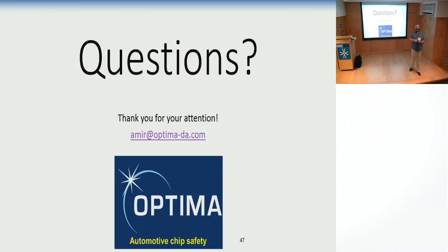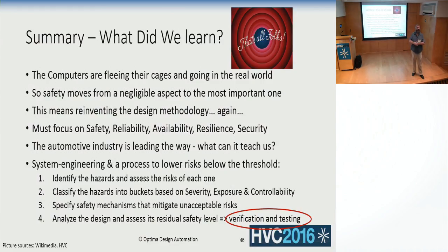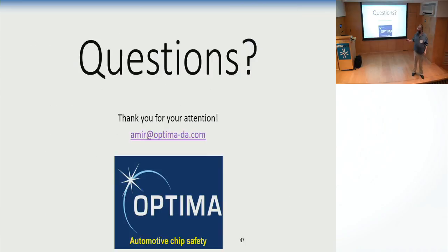We don't use statistical probabilities to figure out where an event will happen, but we do compute the probability that an event will be critical, which is what I mentioned before. Typically these things are not general purpose, they're not running games, they're running very specific hardware and a very specific software sequence. If I simulate this software sequence from time 0 to time n, and each time I have a potential error on this flow,